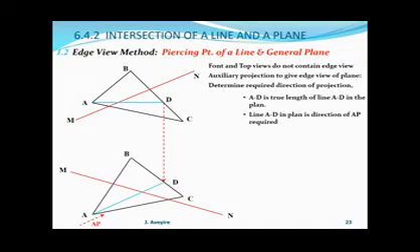Now, for us to perform any auxiliary projection, there are principles we have to follow. First, to determine the mutual view. Now, we are dealing with the top view. Therefore, the mutual view that is available currently is the front view. So we select the front view as the mutual view. Then we need to instruct our mutual projector, MP, which means projecting from the given view, that is the top view, to yield the mutual view.